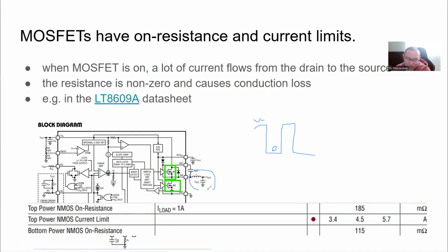And we're then using some kind of LC filter to only pass through low frequency portions of this. We're getting rid of these high frequency transitions. And because of this action, this is not going to be perfect DC at the output. In fact, it's going to have some sort of switching ripple due to this switching frequency and its harmonics, because our filter is not perfect.